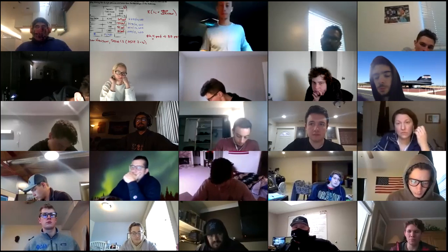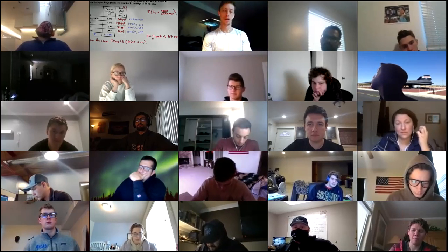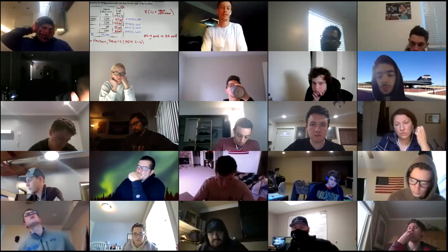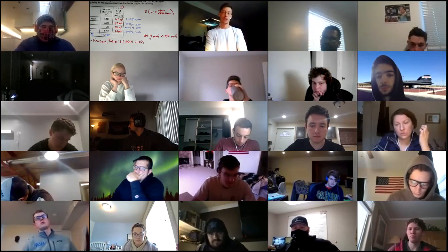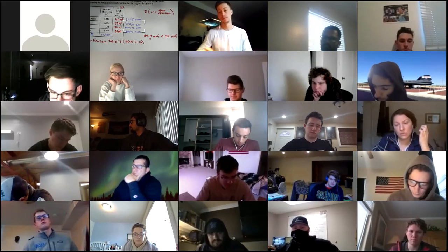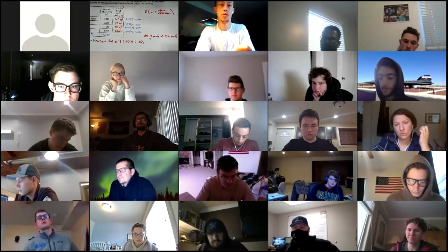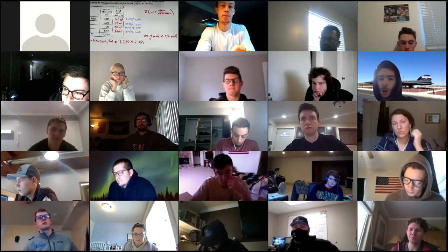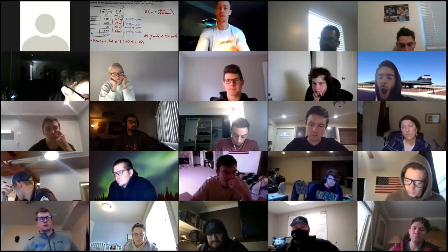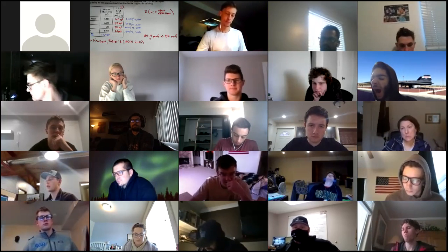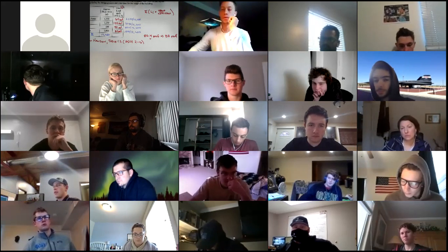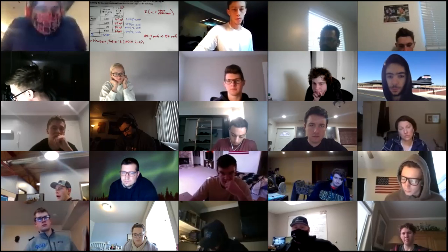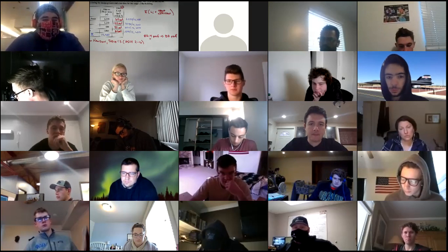I know as a student, you're saying, heck no, this is good enough. I'm turning it in, right? As a professional, you have to do something. Well, then you might say, well, but I got it in the computer. I just changed a number. Well, that's what the architects always think. The problem is they want to change a column by one location by 1 inch. That's going to change the span length on everything. And it's not just so simple as changing it in the structural analysis software and letting the computer do all the work. It changes everything. And if nothing else, you have to review the detail of every single little thing. It is a pain. And so what you do is you hedge your bets.